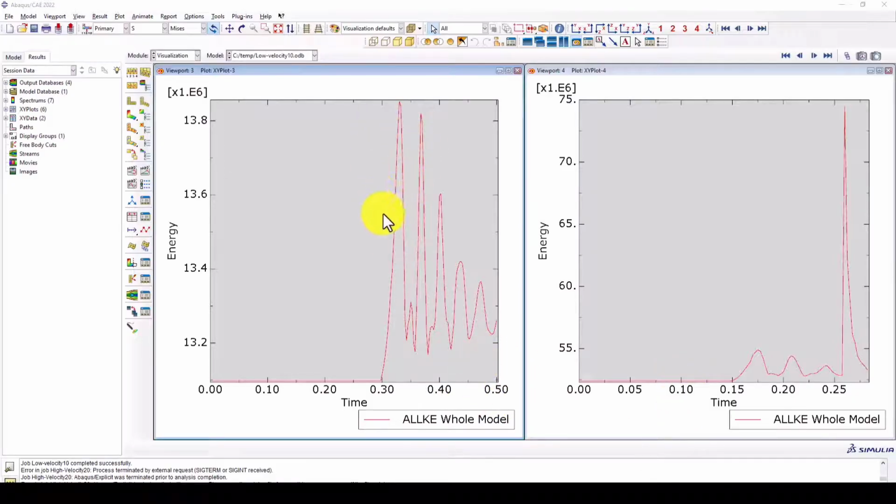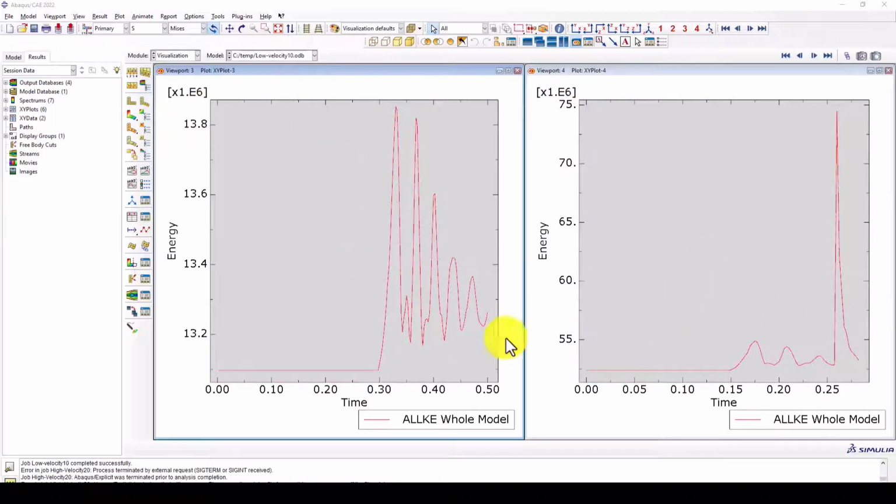Next one is very critical, that is the tangential behavior. This is where the friction becomes very important, and we need to define a friction coefficient. So if a ball is intended to bounce almost vertically without significant sliding friction, this may have a relatively small influence of friction. But if the ball strikes the plate at an angle, or if rotational motion is involved, friction can become much more important.